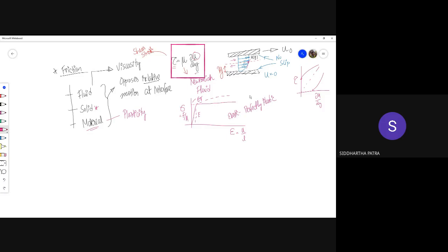So friction, as you might know, is associated with loss in mechanical energy. So mechanical energy is dissipated through friction. And how do I know plasticity is friction? Because when you try to unload in plasticity, let's say you load it like this, if you unload in elasticity, you follow the same curve. But if you want to unload in plasticity, you follow this steep line right here, which is parallel to the elastic part of the curve.